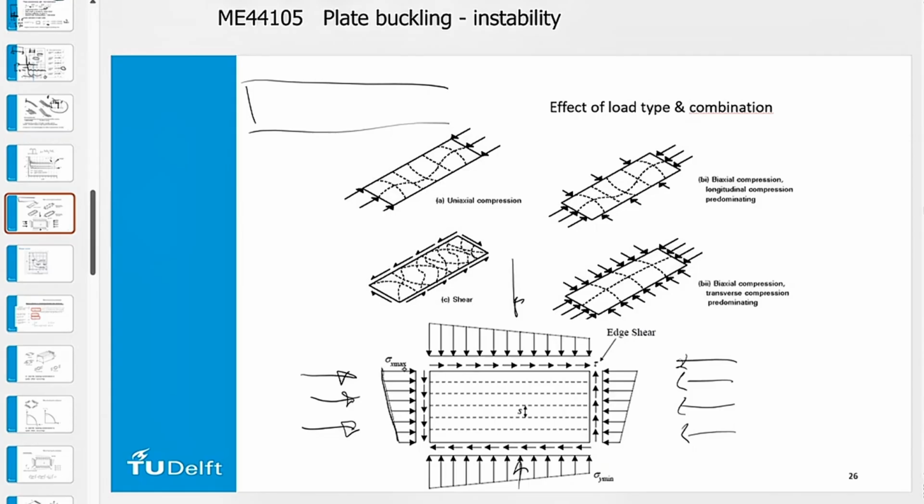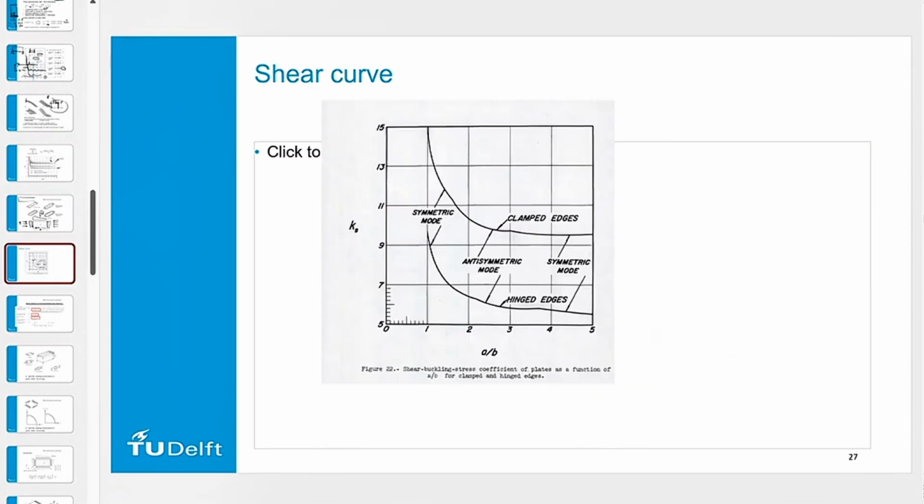Furthermore, you will also have to take into account whether something is bending in both directions or it is uniaxial compression. And then the last thing which we also need to take into account is shear. So we now need to calculate the risk in one direction, the risk in the second direction, and the shear risk. And then we need to combine all these things.